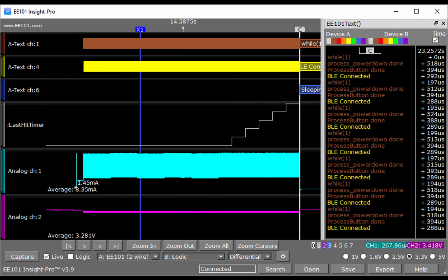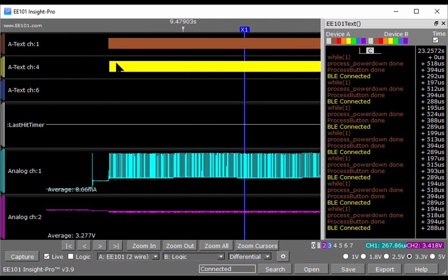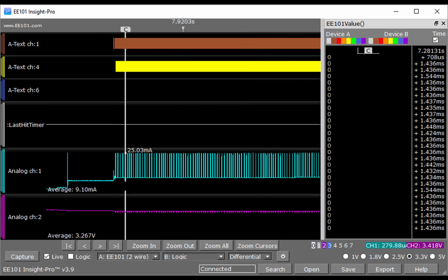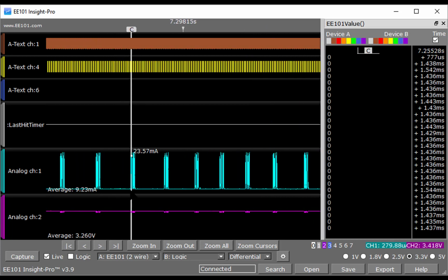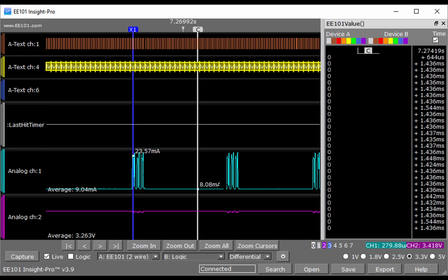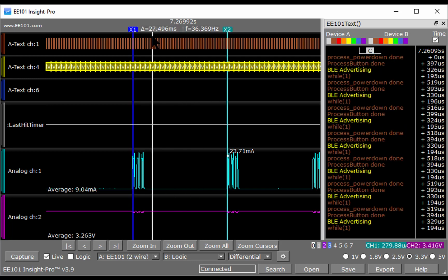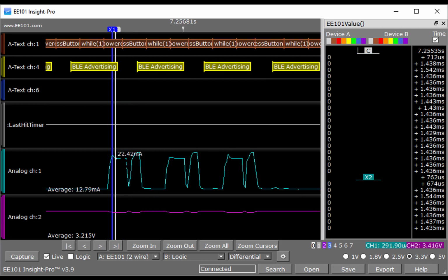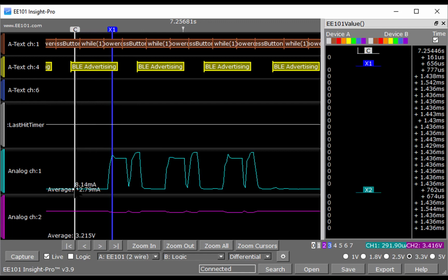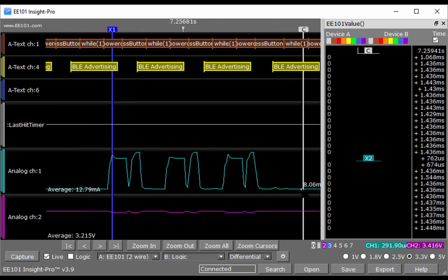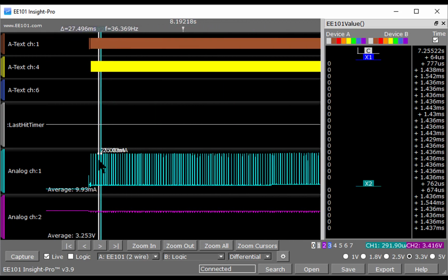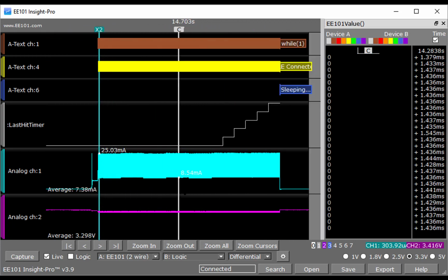And now you can see the characteristic of all the current of the system. You see the current at startup. You can see the advertising pulses on the Bluetooth. In this case, it's advertising at 27.5 millisecond intervals. Those are the 3-channel bursts of the Bluetooth advertising traffic. Sort of idle current in this case is about 8 milliamps. The transmit current is about 20 something, 22.